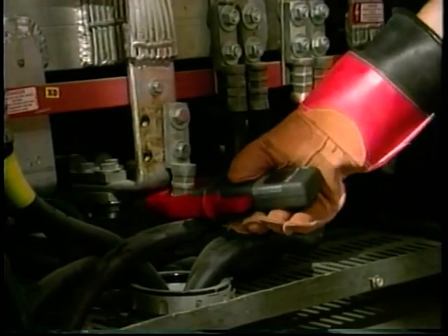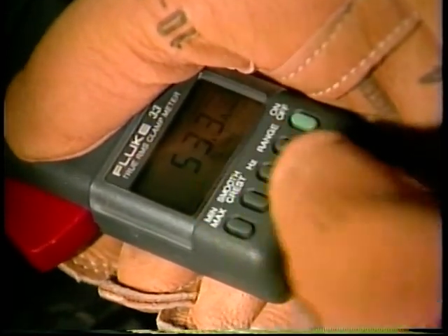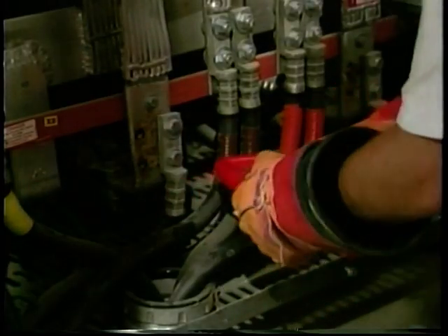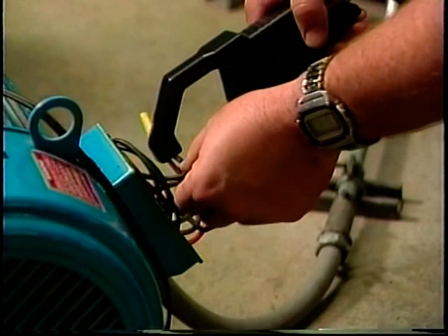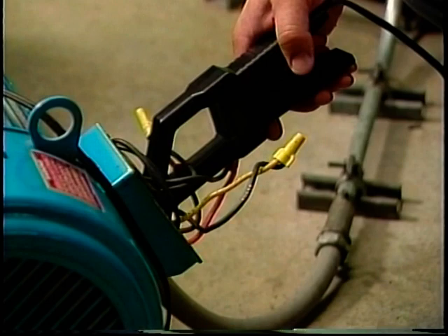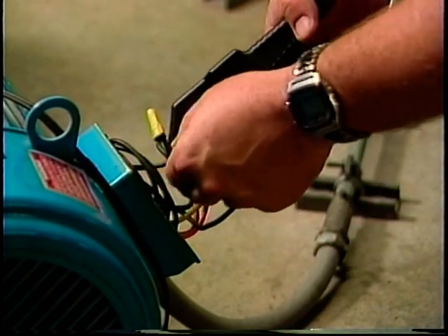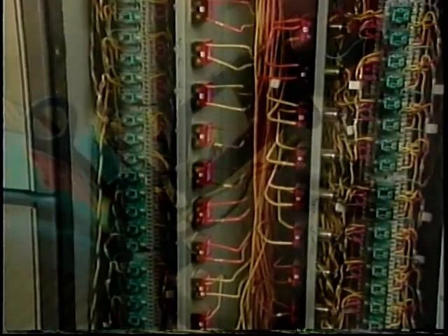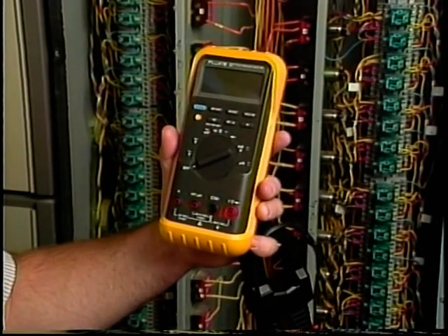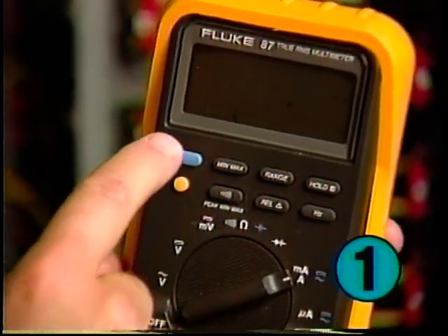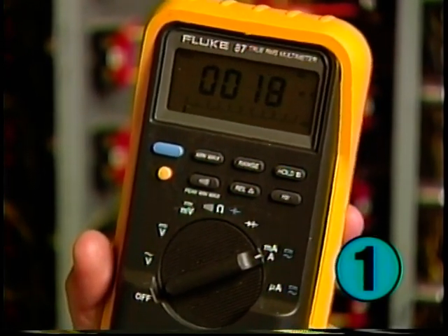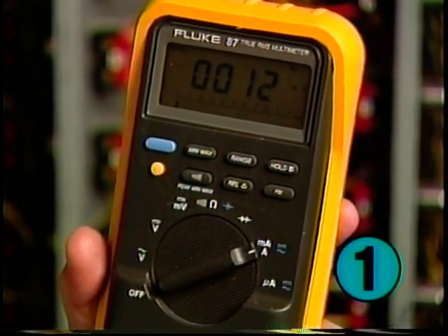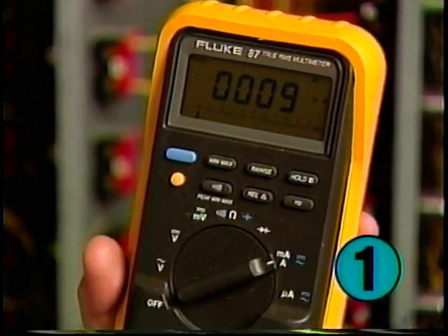Clamp-on ammeters measure the current in a circuit by measuring the strength of the magnetic field around a conductor. Care must be taken to ensure that the meter does not pick up stray magnetic fields. Whenever possible, separate the conductors under test from other surrounding conductors by a few inches. To measure AC using a clamp-on current probe accessory, apply the procedure: 1. Set the function switch to AC current. Select the proper setting to measure the highest possible circuit current if the meter has more than one current position or if the circuit current is unknown.